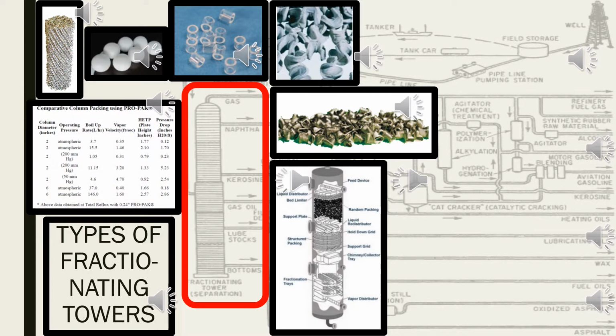You should use packings as passive devices that are designed to increase the interfacial area for vapor-liquid contact, without causing excessive pressure drop across a packed column. This is important, because a high pressure drop would mean that more energy is required to drive the vapor up the distillation column. Examples of pressure drops you can refer to are given in the table, in this case for